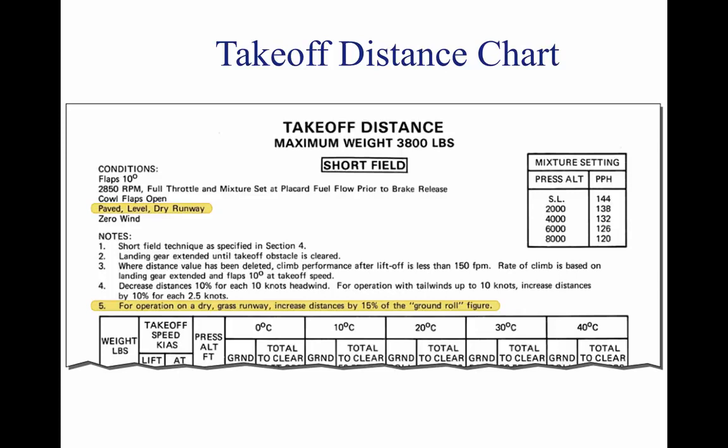The speed, acceleration and deceleration experienced by any object varies directly with the imbalance of force and inversely with the mass of the object. An airplane on the runway moving at 75 knots has 4 times the energy it has traveling at 37 knots. Thus, an airplane requires 4 times as much distance to stop as required at half the speed. The takeoff or landing roll distance is a function of both acceleration, deceleration, and speed.